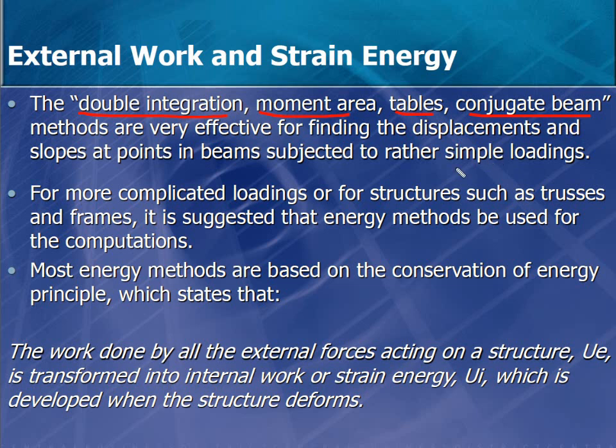But if you realize, I'm saying beams. I'm not talking about trusses or frames, so I cannot use the above-mentioned methods to calculate deflection for trusses or for frames. So in order to find deflection for all of them, we can use the energy method, which is a general method for calculating deflection. So it can be a beam, truss, or frame. Now the idea of energy methods is based on the elastic behavior of the material.